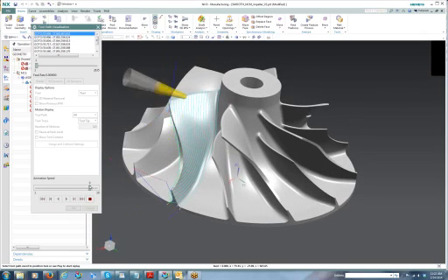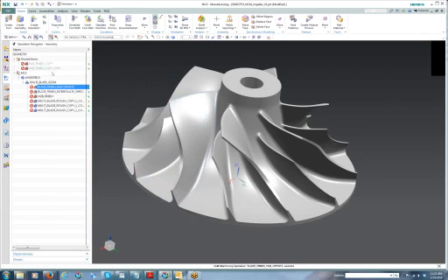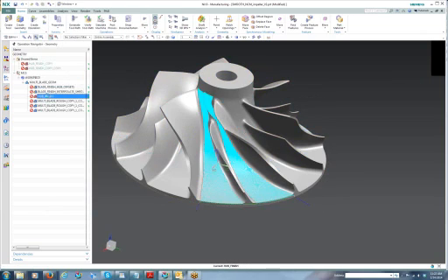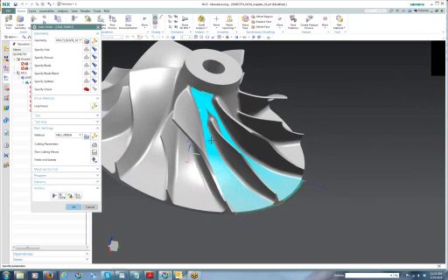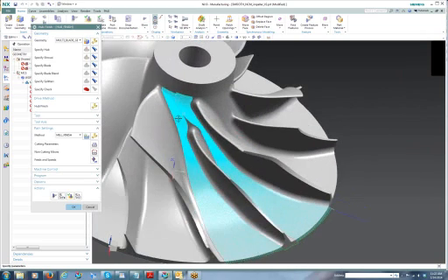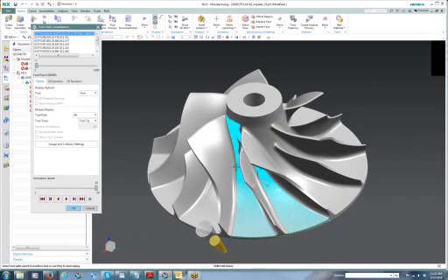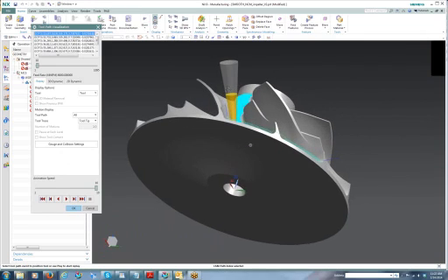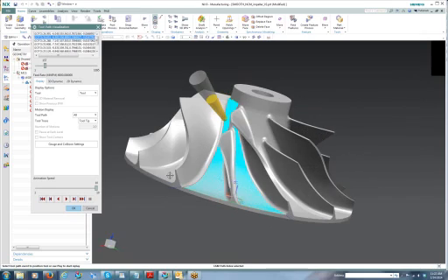So we're using a technique very similar to the last example with the contour profile, where we're now just working our way around that blade. So that's an example of the Swarf machining. Then we can go into the hub finish, and here it's automatically working between the two blades, and it sees the splitter, and it's giving us a smooth tool path. Again, it's constantly aware of the rest of the part, so we're able to use a tapered ball end mill and keep our stiffness up.